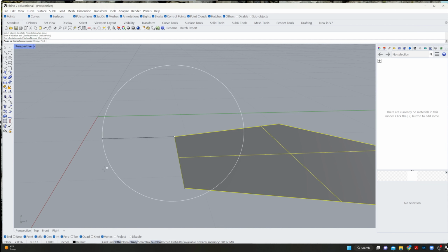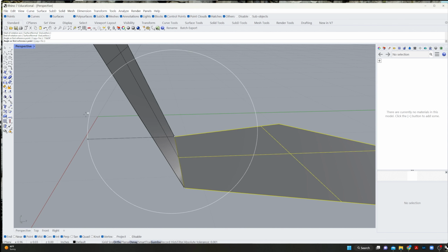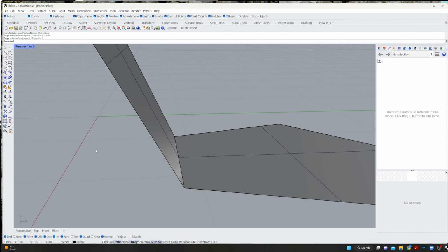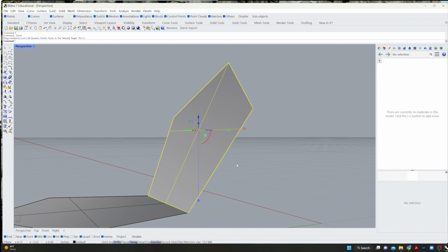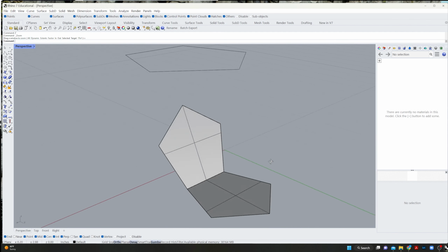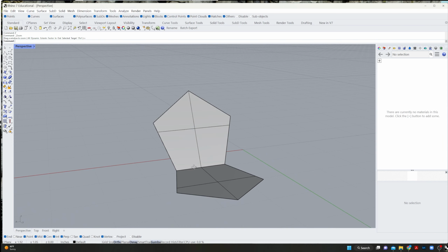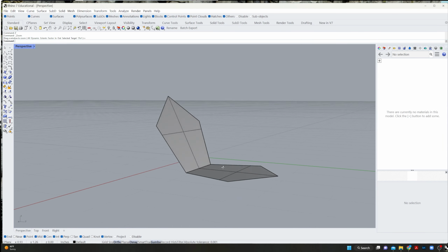Then I'm going to select an axis point from here to here, and then pull out this way. I'm going to make sure copy is set to yes here. Then it says angle or reference point, and we're going to do 116 degrees, D for degrees, 34 apostrophe. Enter. All right, and enter again to get out of the command. I'm going to hit Z, enter, S, enter to zoom in on my selected object.